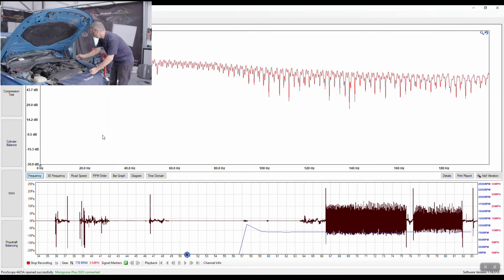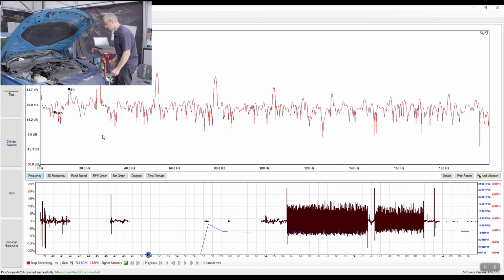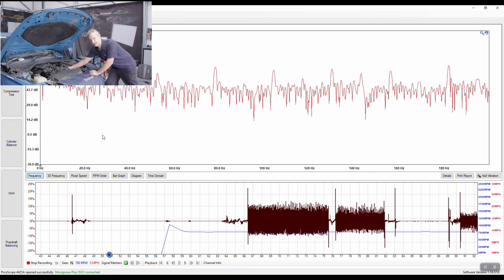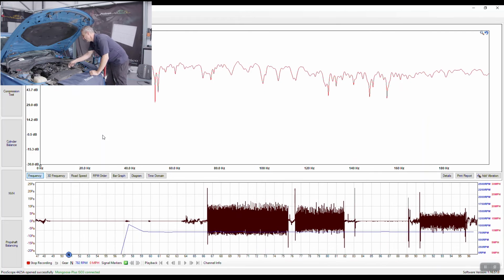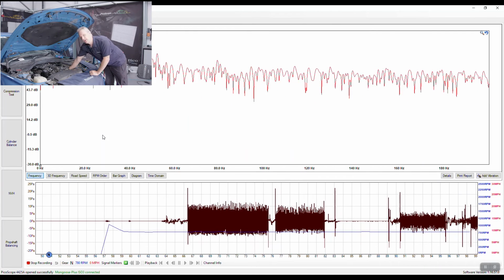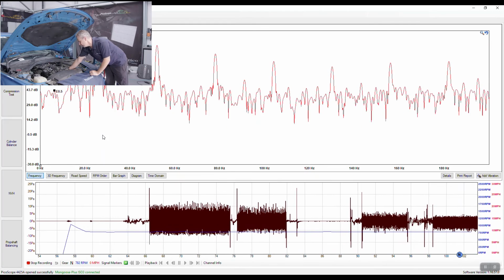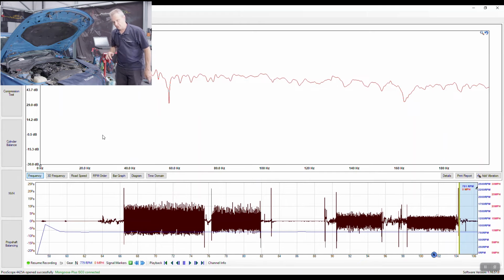We'll then come onto the chassis where there's virtually no vibration, no audio. We'll now go down onto the alternator, and I'm holding it on the alternator because it's aluminium. I'll take it off there and I'll reach down and get onto the air conditioning pipe. And we'll finally take that off. We'll pause the software, which we can do with the space bar, and then switch off the engine.